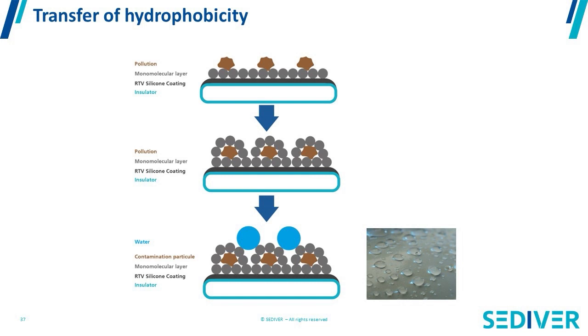Now, my story is right, but in fact, it is not. Of course, a silicone surface will remain dry, but you will not prevent dust from accumulating on the surface of the insulator. So at the end of the day, I have an insulator that is nice and hydrophobic, but still, on the surface, I will have my dust. My dust is still going to come on it. The beauty of silicone rubber is that this hydrophobic property will actually migrate through the pollution layer in such a way that the pollution layer itself becomes hydrophobic.